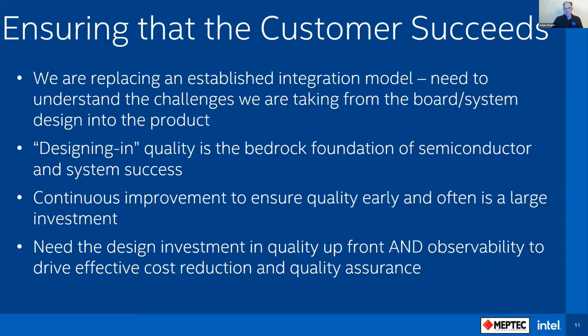If I'm integrating functions into silicon, that's a well understood problem in the fab and product design. As we take designs in silicon from different vendors and stick them together within a package, that is a completely different model. We're relying a lot on the capabilities of other vendors to make sure our system comes together well. Designing in quality is the bedrock foundation of semiconductor and system success. With EMIBs, chip-to-chip seems like a simple test problem. It's easy to talk away, like, just a wire running at a reasonably slow speed.